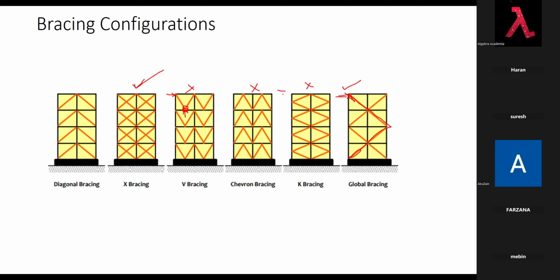They are not using this kind for seismic behavior, because when the horizontal load is applied, the load from here is transferred to this column. So this column is suddenly subjected to more point load here, like a beam-column element. We can construct anything, any method, but we need to choose which one is optimum, which one will give me the smallest column section and the smallest reinforcement. So mostly in this configuration they go for these two methods.